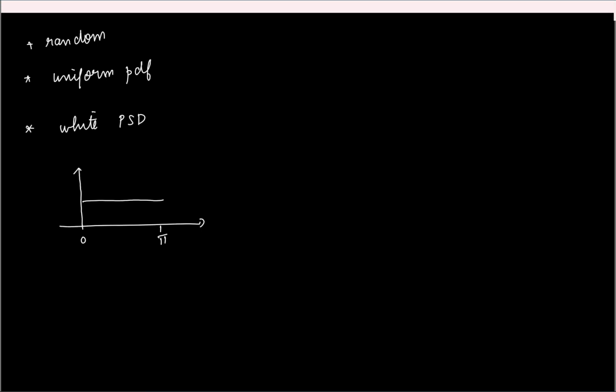And again, all these assumptions actually hold good in practice as long as you have those busy signals. Right? And remember, what is the quantization noise power? It is delta square by 12. And how can I compute it from the power spectral density? Yeah, in discrete time I'll have 1 by 2 pi and then integrate it from minus pi to pi.